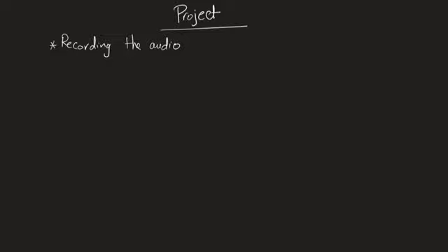Okay? And you will notice that whatever tool you use, there will be something called sample frequency, and or sampling time. The dual of this is sampling time. Either called Fs or this one is called Ts, okay?